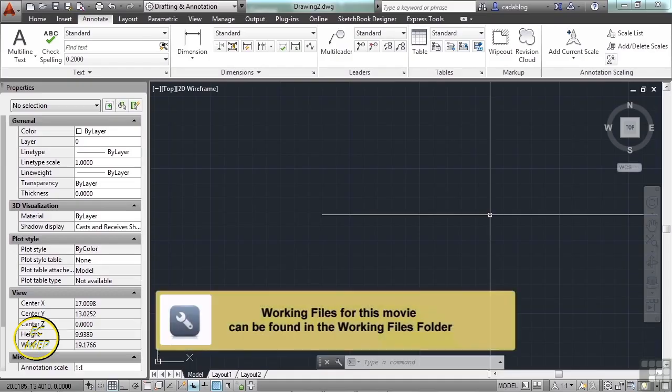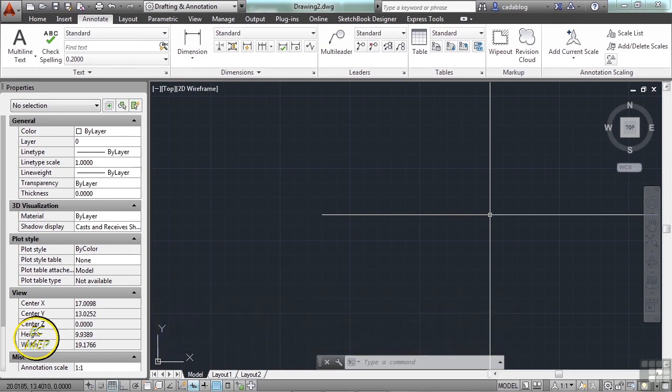There are many different ways to use text, especially multi-line text. The method you use will depend on your needs. Styles will control your font type. MText objects can be edited within the text editor, but once you do, you lose some editing abilities. Let's open up and insert some text, and I'll show you how.